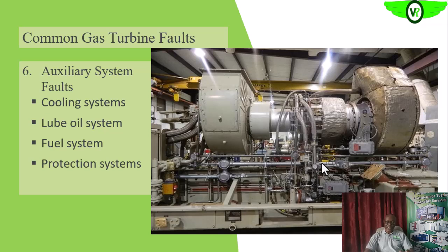So that protection system, there could be faults in it, and if so, when such conditions are developing, it will not see the condition, and the condition will develop and destroy the gas turbine. So we want to ensure that our protection systems are functioning optimally. The overspeed, high temperature, vibration, are we getting it? Lube oil failure, lube oil pressure level, cooling system. Once the cooling system pressure goes below a certain level, the protection system should kick in. The fire and gas, that is the fire protection system too. All of them should be functioning optimally.